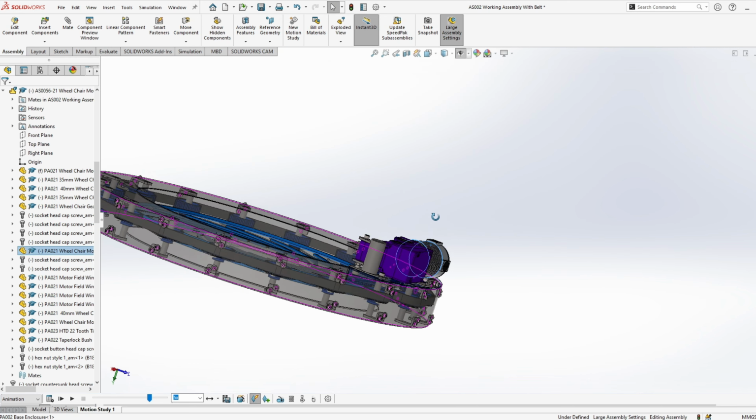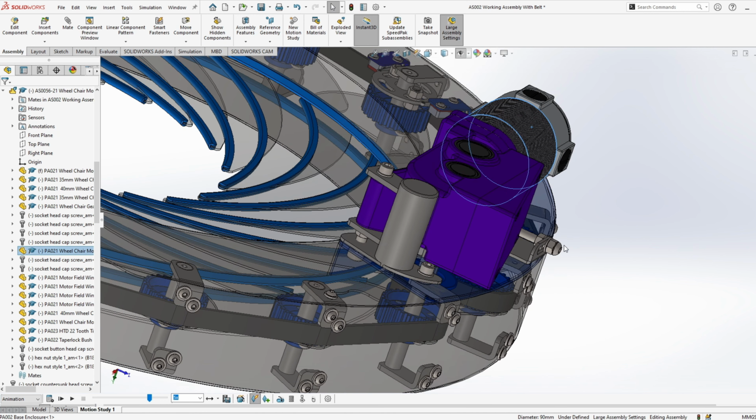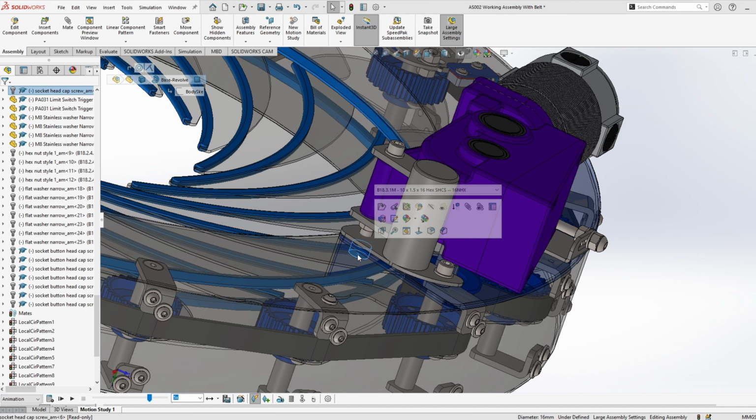So now that I've discussed how it works, I'm going to discuss how it's fixed to the platform. The bracket is directly fixed here using an M10 cap bolt at this end, which protrudes up through this platform and into the tapped hole of the stainless steel bracket.